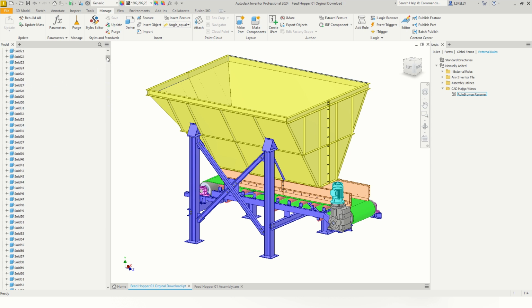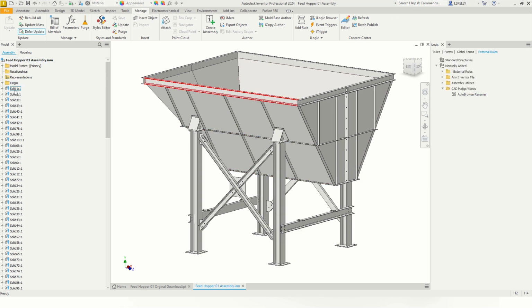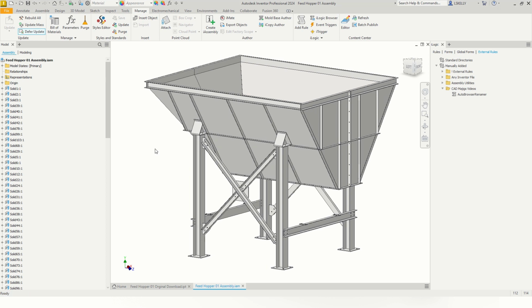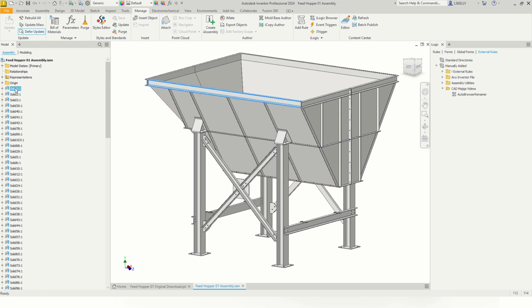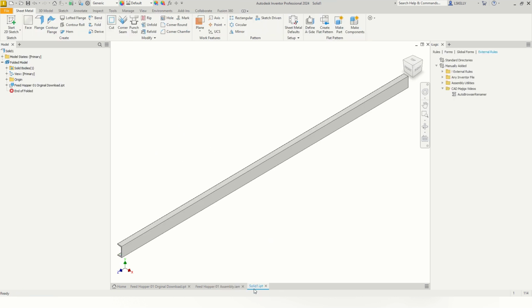It's saved into an Inventor part, and then when I used the Make Components feature, I ended up with this assembly that has these individual parts in the assembly. So we are left with an assembly with parts in it called things like Solid 1, Solid 2, Solid 3. That is the way that these parts were generated using the Make Components function. So if we open one of these parts, we can even see, yes, its file name itself is Solid 1.